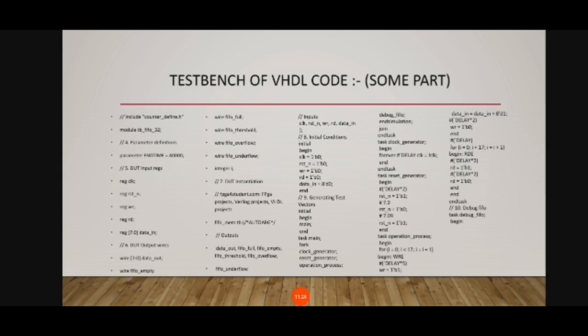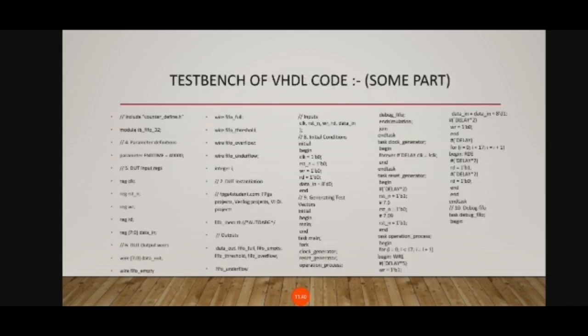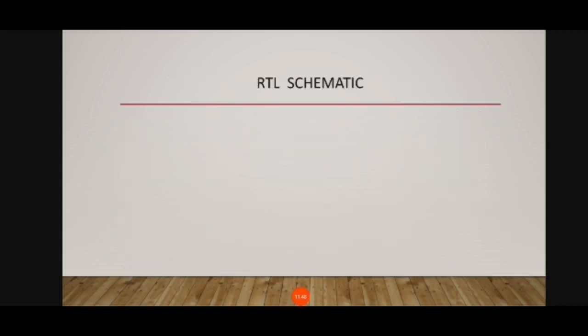A test bench is HDL code that allows us to provide a documented, repeatable set of stimuli that is portable across different simulators. A test bench consists of an entity without any IO ports, the design instantiated as a component, clock inputs and various stimulus inputs. RTL schematics.